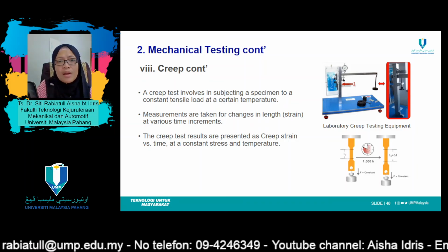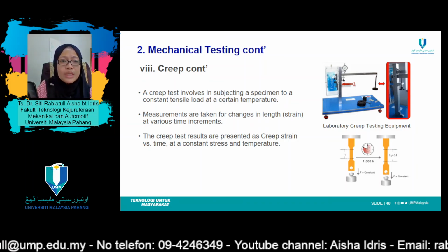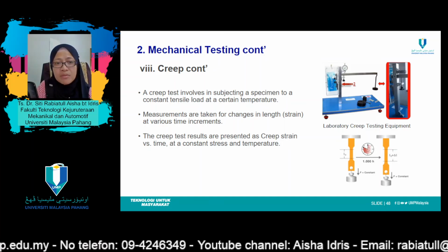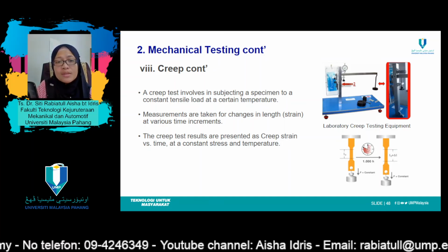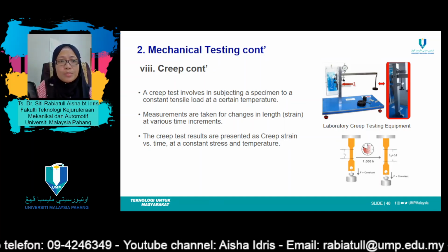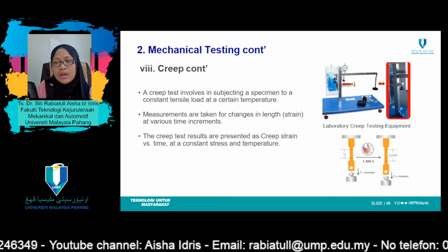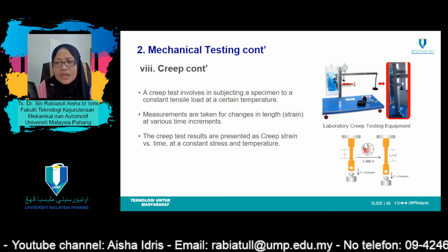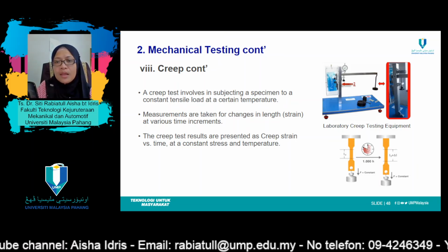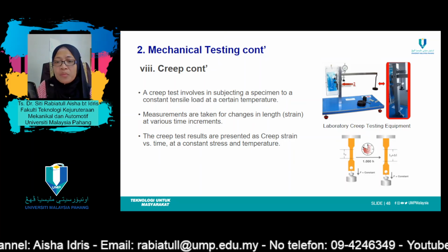Most tests are the constant load type, which yield information of an engineering nature. Constant stress tests are employed to provide a better understanding of the mechanism of creep. So this figure represents a typical test for creep.